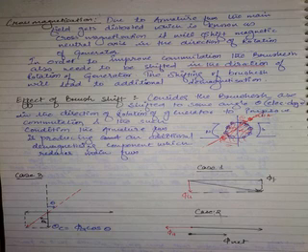So we will be discussing that in the commutation topic. What are the methods to improve commutation? Brush shifting is the first method to reduce armature reaction effect or to improve commutation. That's the way it is. This is a topic important for only competitive exams, but generally this is not done in any DC machines. Now we are not shifting the brushes.